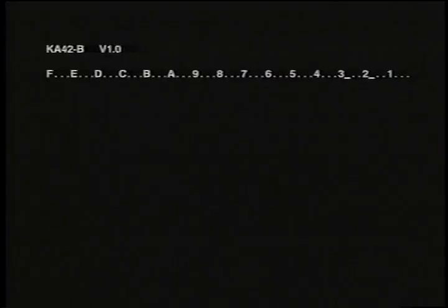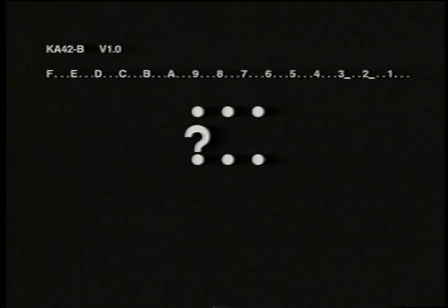Each hexadecimal value is followed by a code. 3 periods indicate a successful pass. Other codes include a question mark, which always indicates a fatal error. An underscore indicates the option's not installed. An asterisk indicates an option's diagnostic ROM code is corrupt. The option must be replaced.